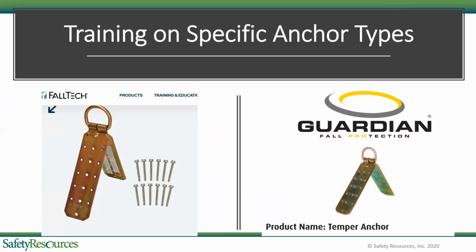Yeah, I just want to make sure that everybody else understands that. So thank you. Yeah, on the low slope one, I remember this slide, we used an example of a corrugated steel roof. And in order for you to use one of these anchors, you actually had to put blocking in between each valley and fasten it down and then have that at the appropriate angle.